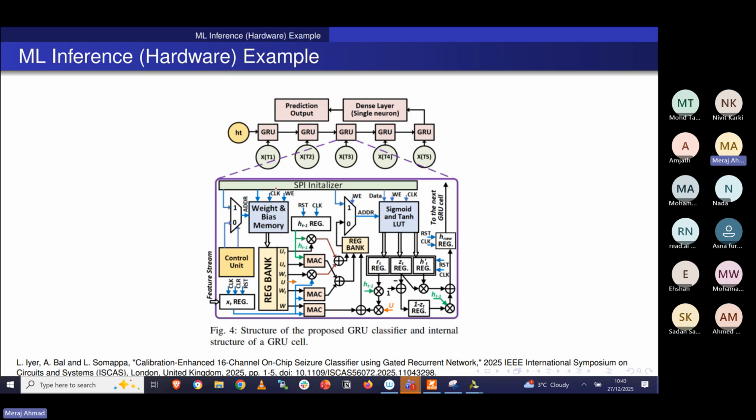You will have write enable, clock, data in coming from outside, and data out. There are various ways in which you can implement memory. Some are in hardware like RAM. Sometimes you need ROM, and sometimes in an FPGA you have LUT RAM. Sometimes you can also implement a FIFO. It depends totally on the requirement.